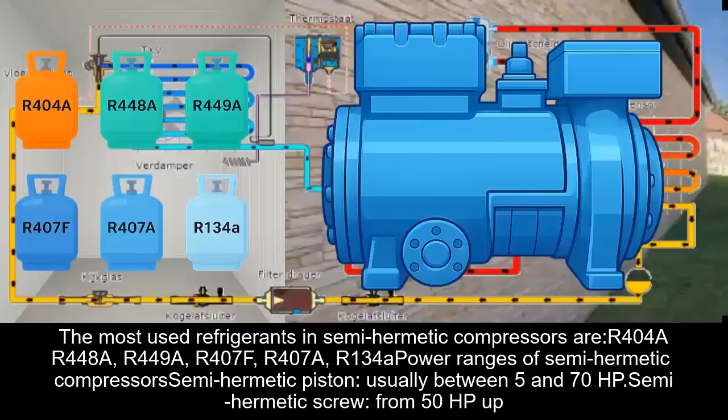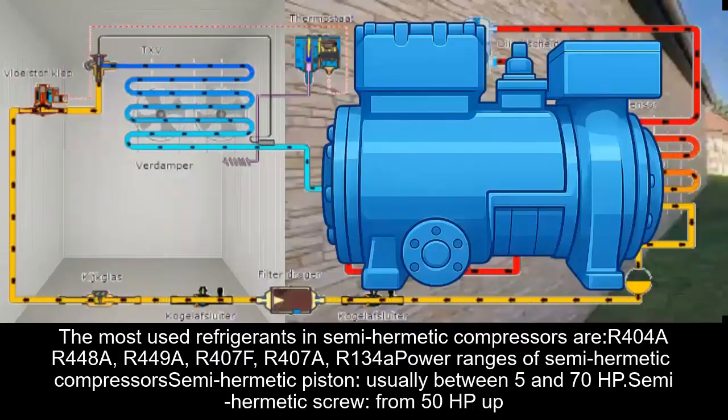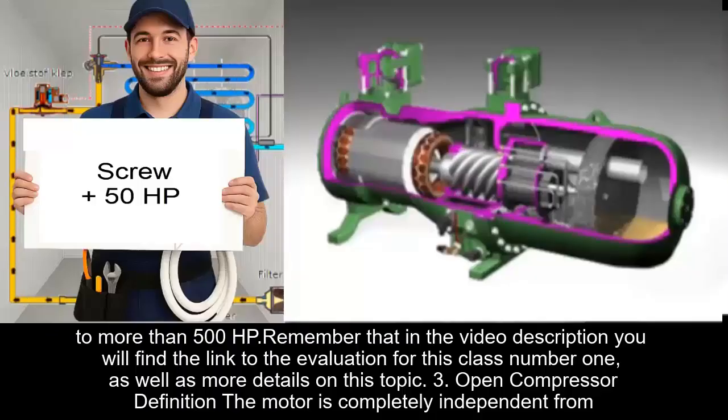Power ranges of semi-hermetic compressors. Semi-hermetic piston, usually between 5 and 70 HP. Semi-hermetic screw, from 50 HP up to more than 500 HP.